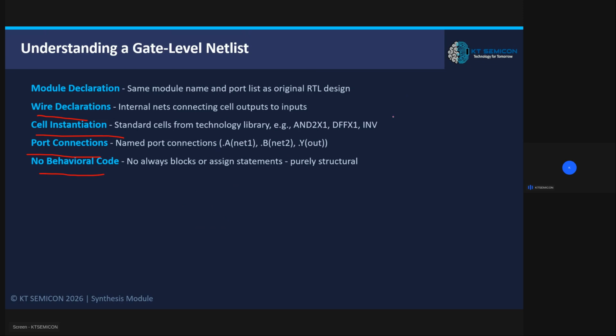Okay, so in this, check here. In a particular RTL code, we have only the AND gate name, but for this we have a particular drive strength and input pins also. And these are the net names, which type of net we are using, and the name of the net. All these things are present in the gate level netlist file.